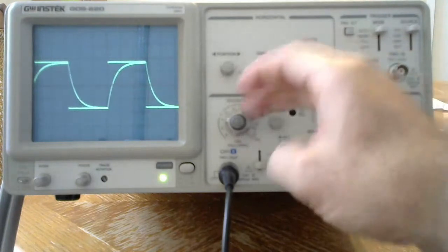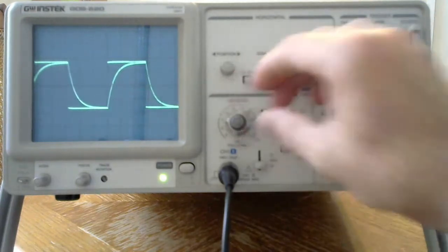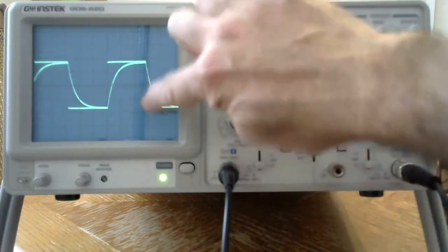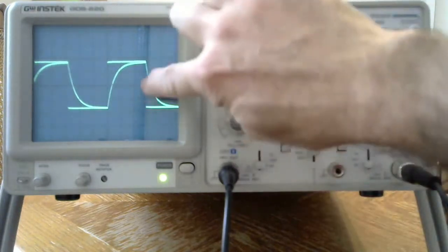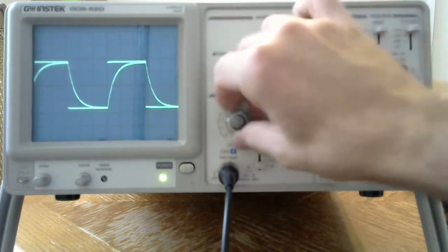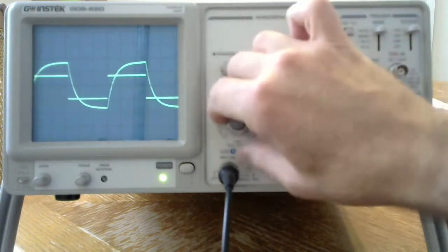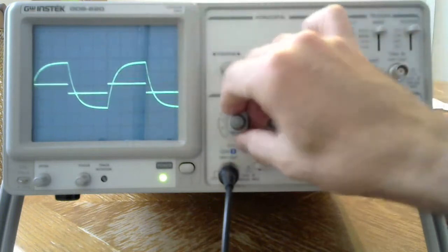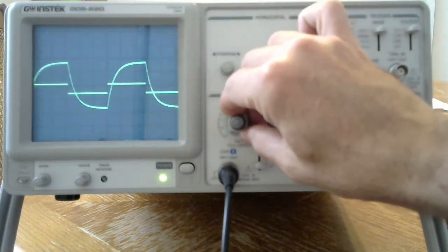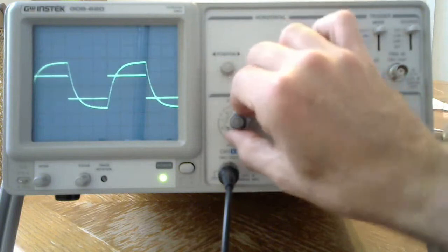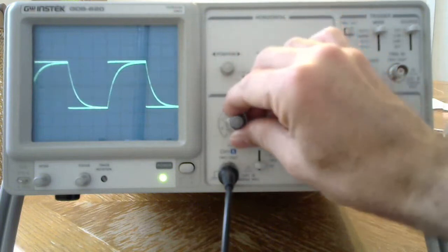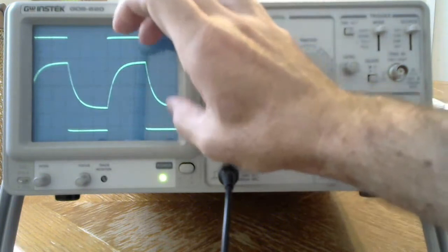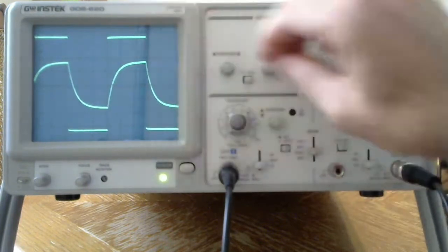And I can do the same thing with this scale for the square wave. So right now it's on 1 volt per division. So each vertical box represents 1 volt, okay? Here, each one represents 2 volts. Each box represents 5 volts. And then going back up again, 2 volts per box, 1 volt per box, half a volt per box. You can see the same signal is expanded because you're zooming in on the signal.